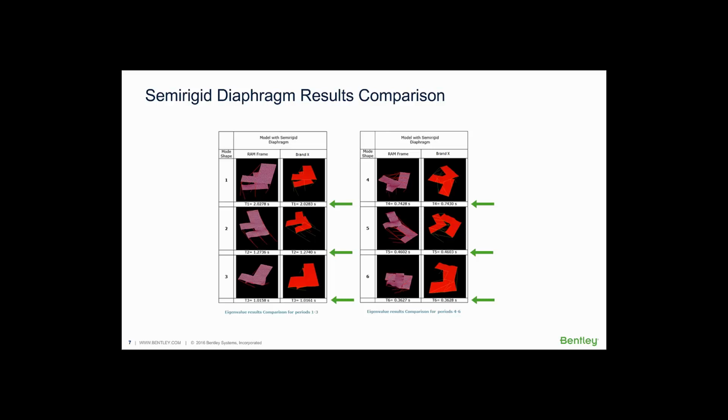But that's a mode issue, and the signs really are irrelevant, because we could multiply the one set of mode shapes by -1 without changing the answer, and then the graphics would have been the same. So I just wanted to note that the reason the graphics look different is just merely because in the one program the sign convention is opposite from the other in terms of how they draw that. But the periods compare, once again, very, very similarly.